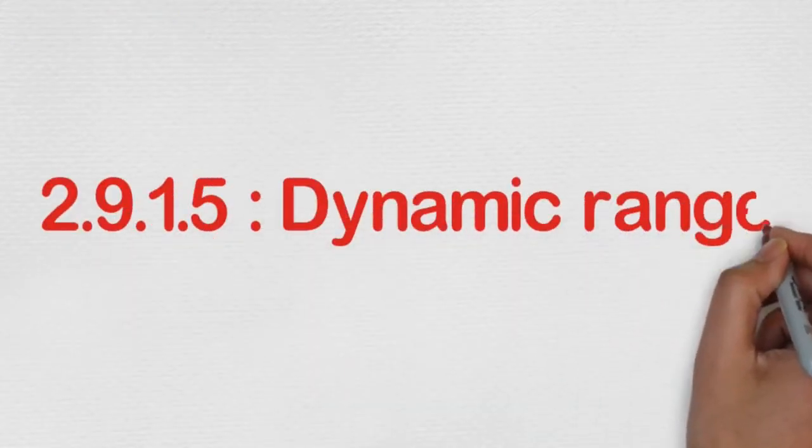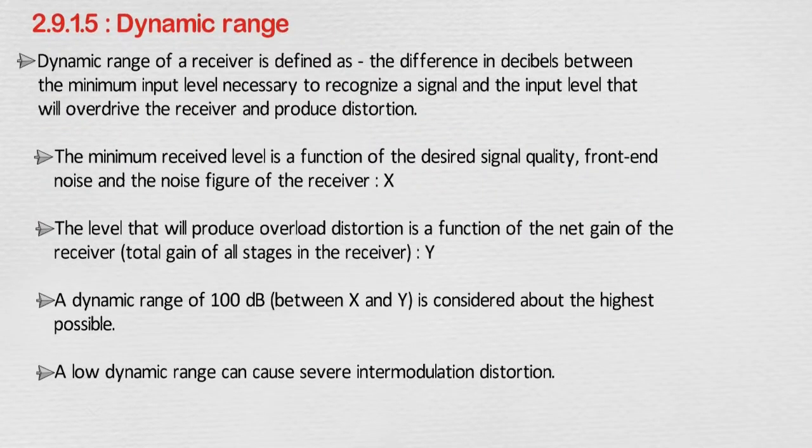2.9.1.5 Dynamic range. Dynamic range of a receiver is defined as the difference in decibels between the minimum input level necessary to recognize a signal and the input level that will overdrive the receiver and produce distortion. The minimum received level is a function of the desired signal quality, front-end noise, and the noise figure of the receiver, X. The level that will produce overload distortion is a function of the net gain of the receiver, total gain of all stages in the receiver, Y. A dynamic range of 100 dB, between X and Y, is considered about the highest possible. A low dynamic range can cause severe intermodulation distortion.